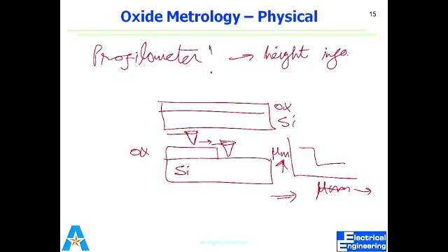But you know that it's more difficult, because one thing, you should be able to have a clear step height. It should not be that you could not manage to save this silicon layer from getting oxidized. If it is getting oxidized, the answer would not be accurate. And secondly, mechanically you need to do this, so you should exactly know where the step height is. If I don't know that at this point the step height should give me the silicon dioxide thickness, I cannot use the profilometer.